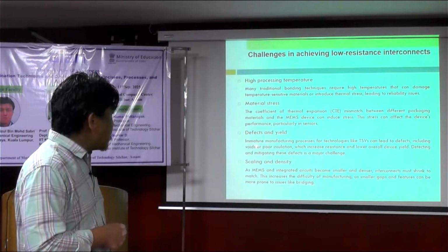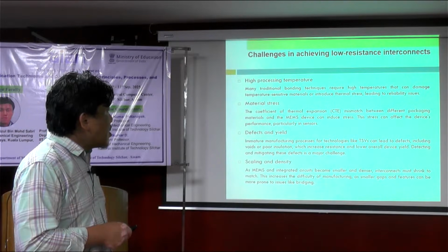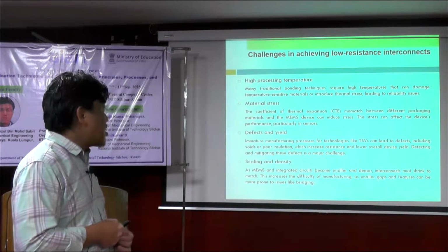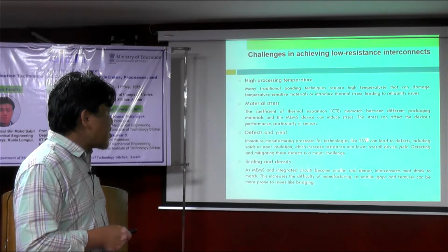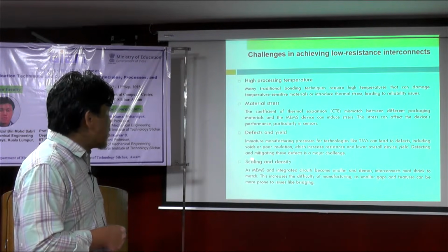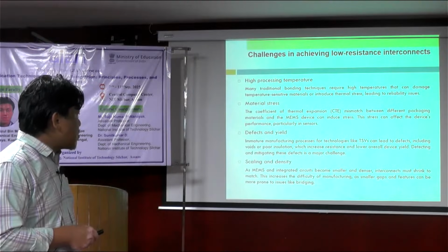And defect and yield, immature manufacturing process for technologies like TSV. TSV nowadays is quite matured basically, but it's still a difficult task to get done, and can lead to defects, including a void or a poor insulation, which increase resistance and lower overall device yield.